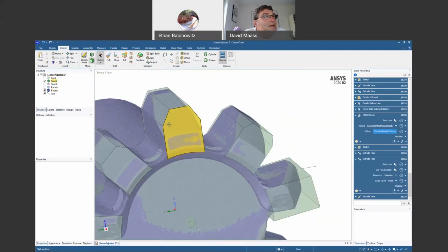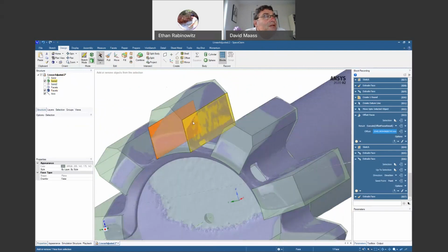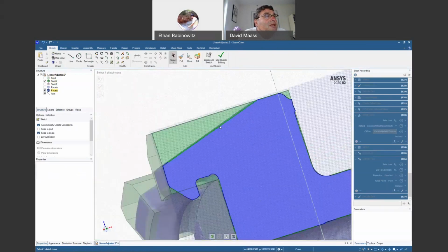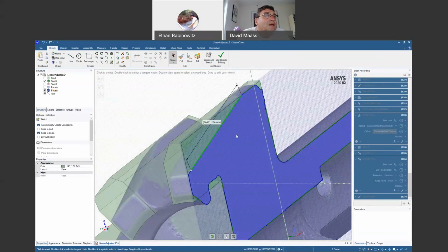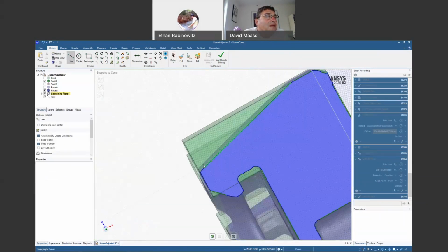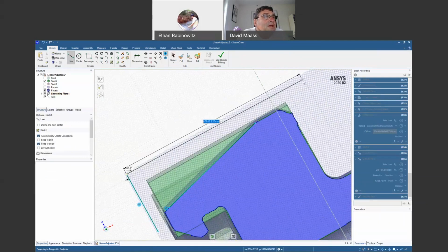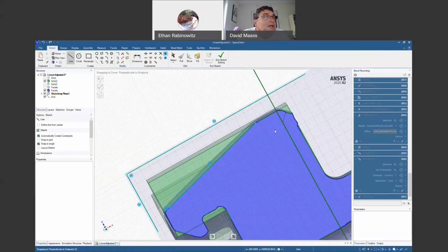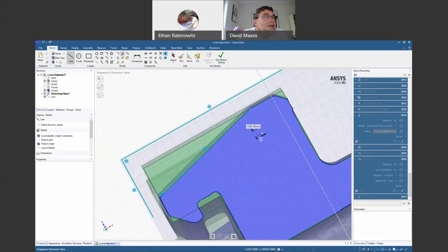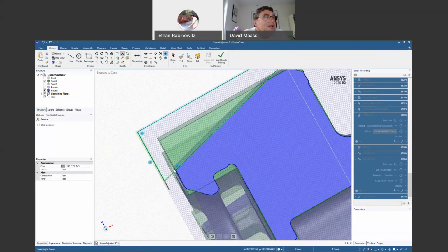So what I'm going to do is grab these two faces and go into a sketch. And very nicely, we have a fit line right here. So I'm going to grab that and copy and paste. And so we've got that. I could snap it, I could sketch right along here, but I'm just going to overextend our cutter. This makes the cutting process more reliable, especially for changes down the line. And then we'll create an extension, a corner from here to there, and from here to there.